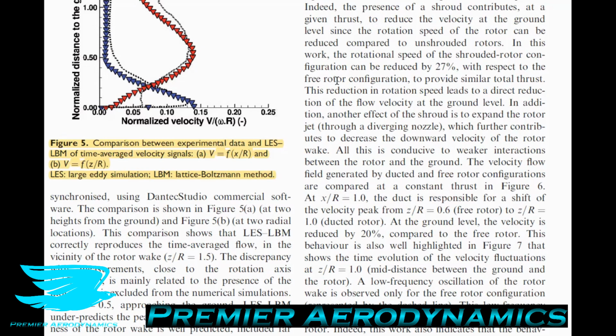So far in this paper, we've seen that the LBM approach is pretty good in terms of the qualitative flow features, and to a certain extent the quantitative flow features as well. And the reason for these discrepancies in the quantitative approach could be due mainly to the grid resolution, which is, again, often sold as a feature and as a benefit, but sometimes it's detrimental.